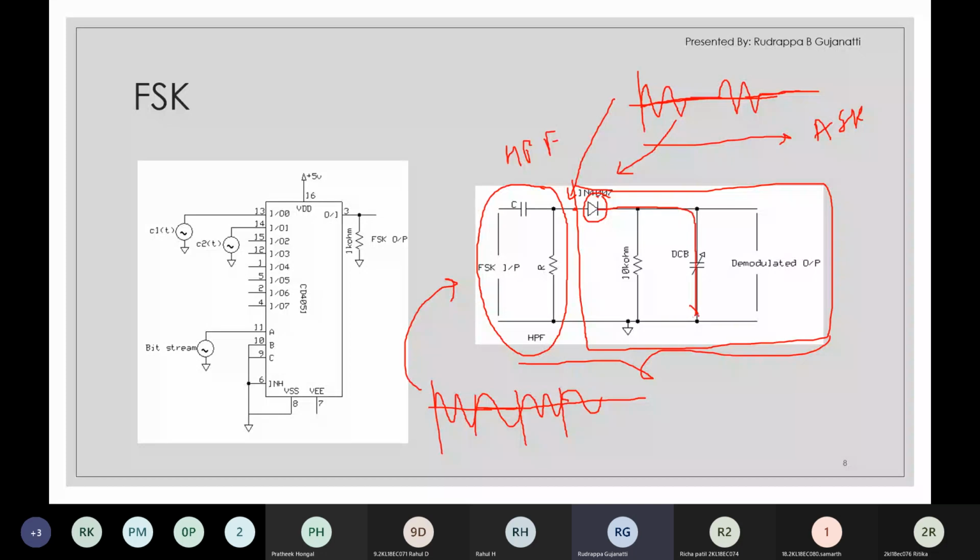the capacitor gets charged. So during the positive half cycle, we get waveforms in this way. Only the positive half cycle is on, and during the negative half cycle, the diode is off. Therefore the capacitor starts to discharge and it might end up with a 0 value.